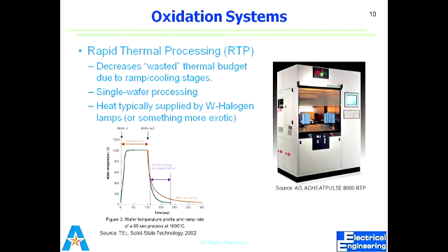Okay, we were talking about the rapid thermal processor, that is RTP. Before going there, in the furnace we can use both wet oxygen and dry oxygen. Yes, in any furnace, it depends on what the ambient is, what the oxidant agent is. That's why I'm using the term oxidant instead of oxygen or steam. So we can use both. What we'll be using tomorrow in the lab would be dry oxide. So in dry oxidation, the oxidant would be oxygen, not steam or water vapors.